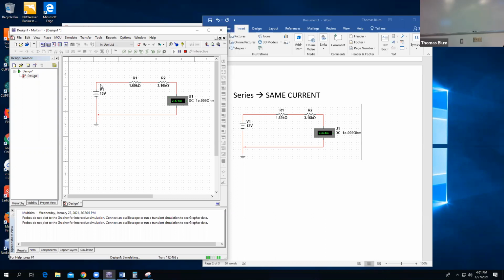What is that useful for? Sometimes when we get to transistors and diodes, one thing we'll learn is they don't like to have too much current, because that will fry. A resistor is kind of a robust thing, whereas a transistor or a diode is a more delicate thing. They're more useful, but they're more delicate. And so sometimes one of the jobs of a resistor is to protect the more delicate things, to take the brunt of anything. So say I have that transistor and I put it in its low resistance mode, that might give me too big of a current and fry the system. But if I have a resistor in there, it will take the brunt and save my system from frying.